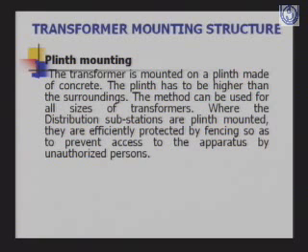Then we have the plinth mounting. The transformer is mounted on a plinth made of concrete. The plinth has to be higher than the surroundings. The method can be used for all sizes of transformers, small capacity as well as large capacity. Where the distribution substations are plinth mounted, they should be efficiently protected by fencing so as to prevent access to the apparatus by unauthorized persons.